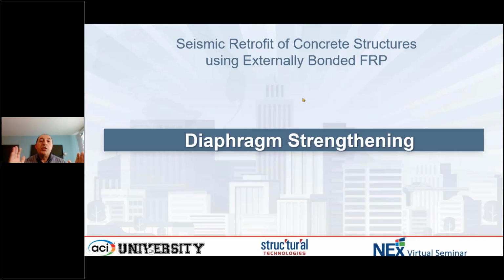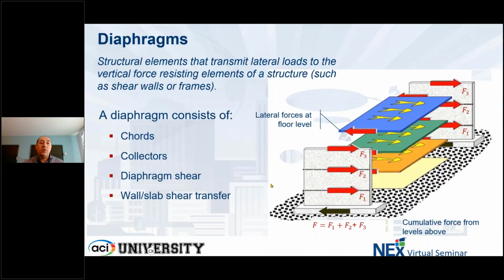Now, the load coming to the shear walls is coming from where? From the diaphragm, right? The slabs within the structure, as they move. They move as a deep element, and they need to transfer the mass, that inertia from the mass times the acceleration from the seismic load, to the wall. So the walls would not do anything unless they have some load, and load comes from the slabs, and the slabs themselves, as they move, have capacity that needs to be achieved, right? And we'll go through that in a little bit more detail.